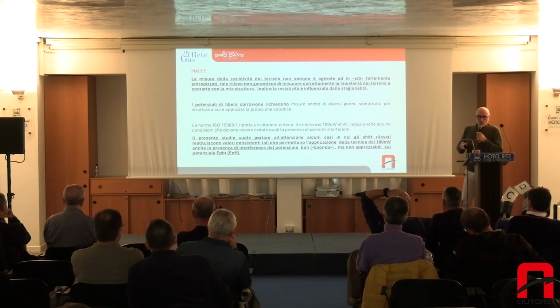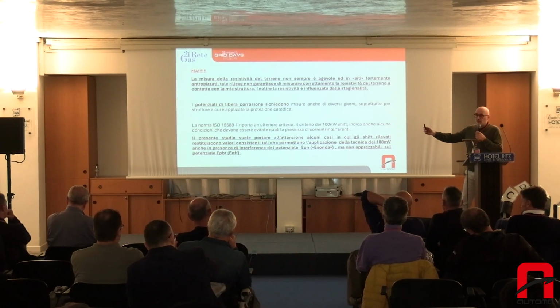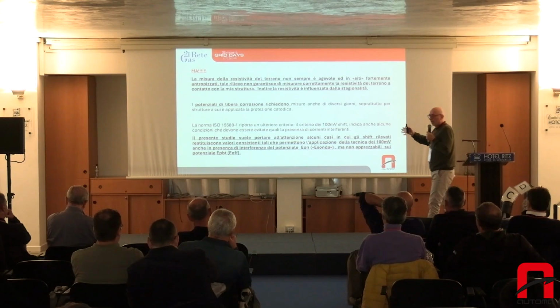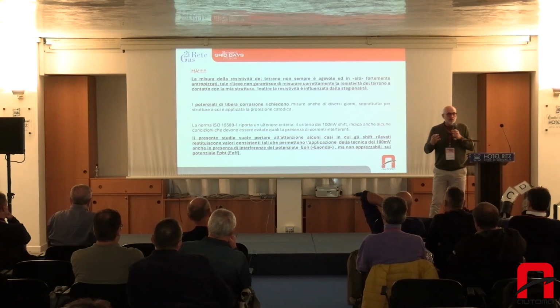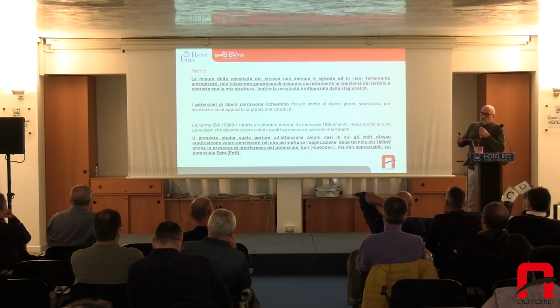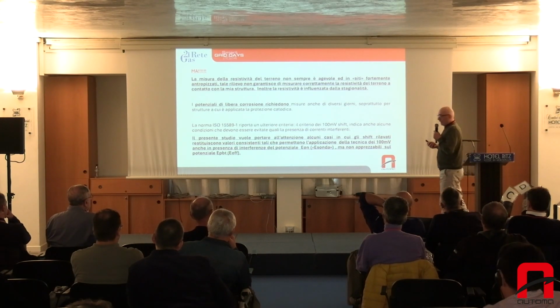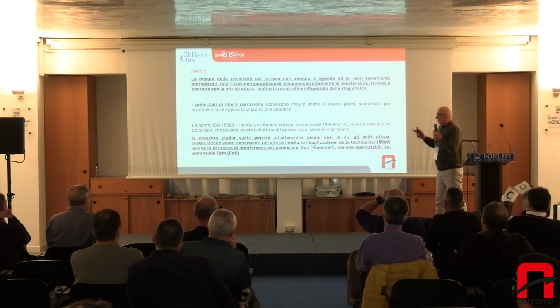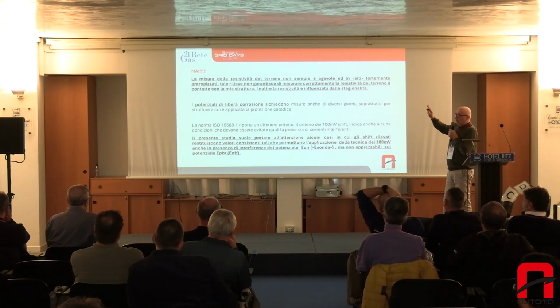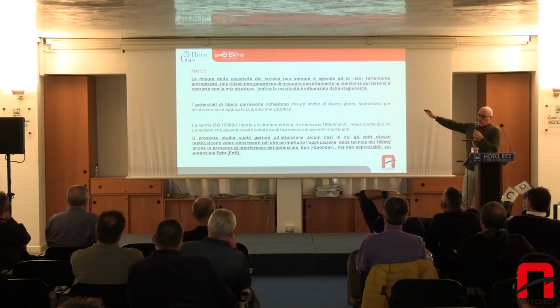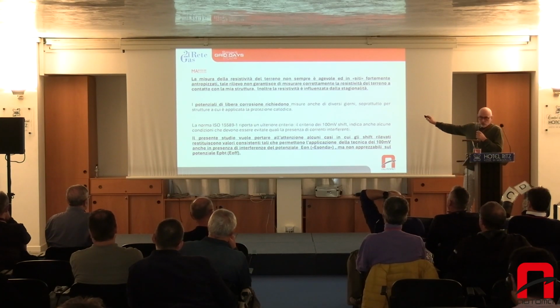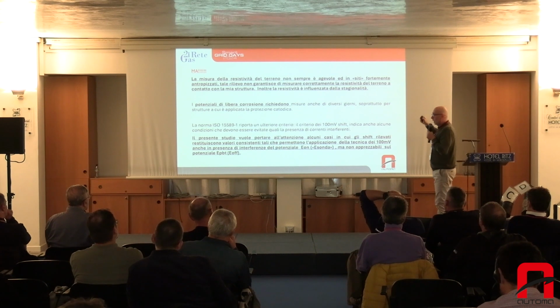Free corrosion for protected plants requires quite some time. It took us about a week. So, okay, it's protected, I switch it off, I wait for 8 days, and then I have 8 days of non-conformity. So if you don't reach a 0.85, you can move the threshold if you have certain figures and data.